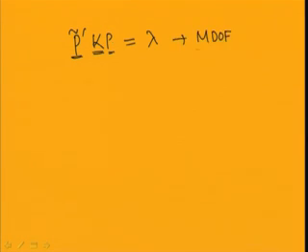Similarly, if you recall this P weighted modal matrix, you have checked that this will become the eigenvalues of the system. So, using this weighted modal matrix, P transpose K P, where K is the stiffness matrix and P is the weighted modal matrix for a multi degree of freedom system, this becomes equal to lambda, that is the eigenvalue of the system.